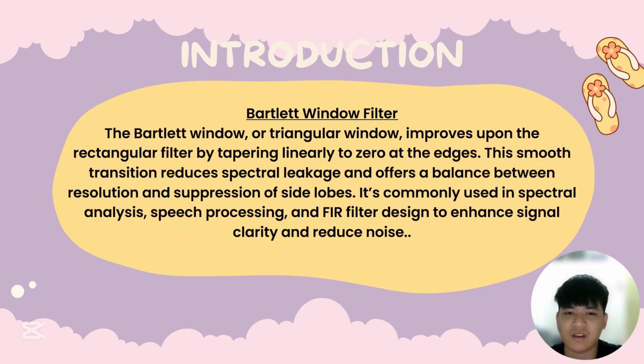window filter, it is the Bartlett window filter. The Bartlett window, also called the triangular window, improves upon the rectangular filter by tapering linearly to zero at the edge. So it gives a smooth transition, reduces spectral leakage, and offers a balance between resolution and suppression of side lobes.